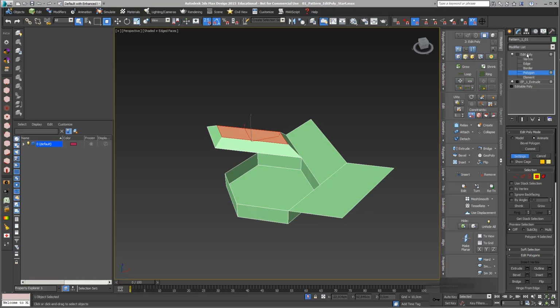Also here we just go and rename it. I go into the modifier and just say right mouse click on Edit Poly, and I go into rename and I call it Edit Poly EP line 2, because this is for me now the polygon number 2, and I just name it bevel and just say enter. Next step, I can actually close it.